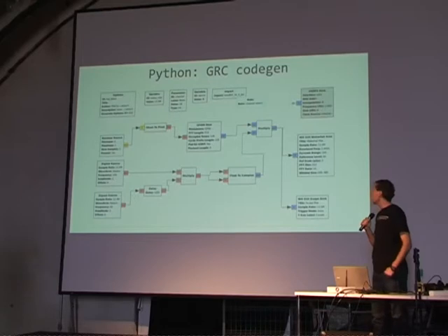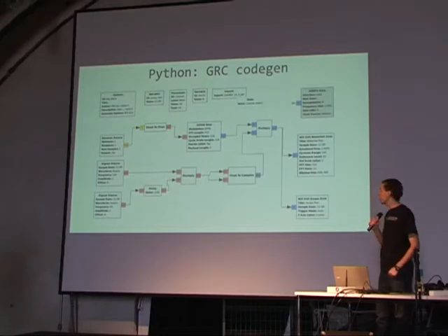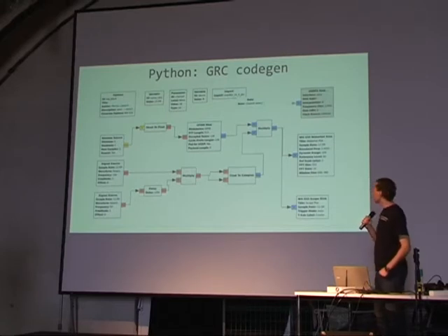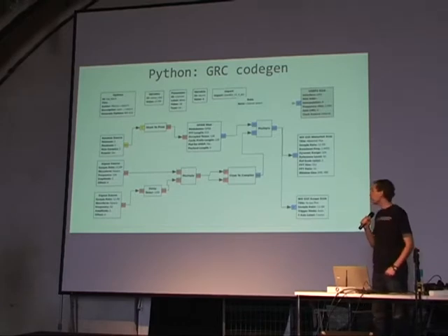So with that, you can verify that your system that you are targeting does appropriate channel changes and therefore continues to work or fails to work. And since IEEE 802.15.4 is used for medical devices that have to cope with interference within the ISM band, this can be a relatively useful scheme to simulate interference in a laboratory environment.